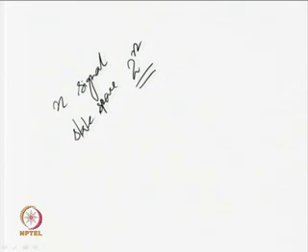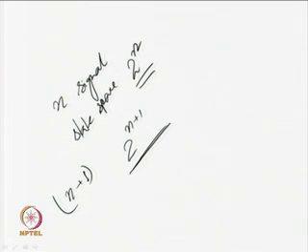Say while designing, we initially started with n signals, but found that it cannot be designed properly. We need one more signal. So, we incorporate one more signal in our design, and the total number of signals becomes n plus 1, and the state space now becomes 2 to the power n plus 1. So, you can see that the state space is exponential in nature, exponential in the number of signals that we have. For a smaller system it is fine, but for a bigger system it is going to give us problems.